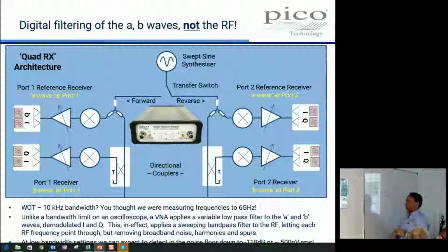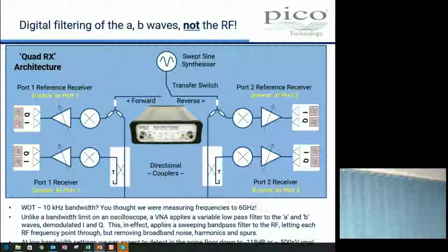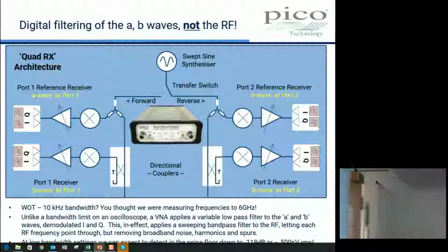the other frequency tracks the 3 gigahertz at 1 megahertz behind it, and we mix the two together and we get an intermediate frequency that we are processing through this amplifier. So the signal coming out of here is a 1 megahertz or thereabouts waveform, and its amplitude and its phase information are all connected to the original 3 gigahertz.